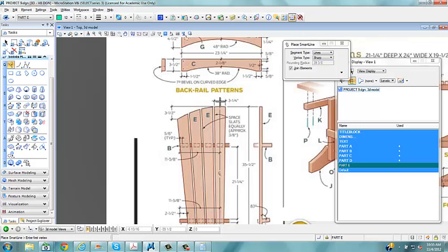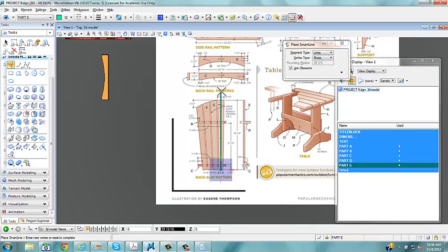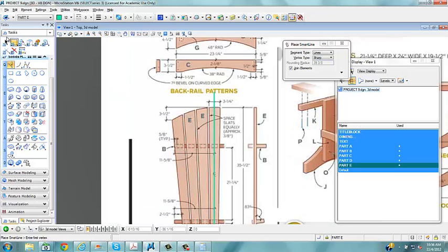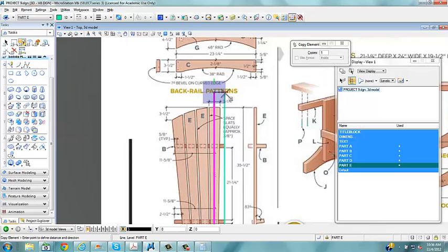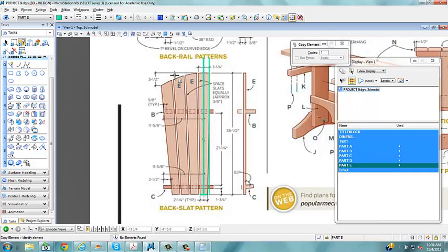Actually it might be easier to think of the best way to keep this centered. Let's do it this way. Let's draw a vertical line, just a temporary one, right up the center. And we're going to go 3 1/4 divided by 2. Just copy this over. 3.25 divided by 2 puts me right on that edge, but I'm just trying to be as accurate as I can. And I want to go above the top, because this actually has a little bit of a radius on it, and we'll try to figure that out as we go.